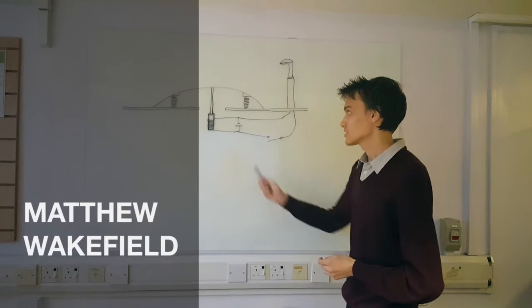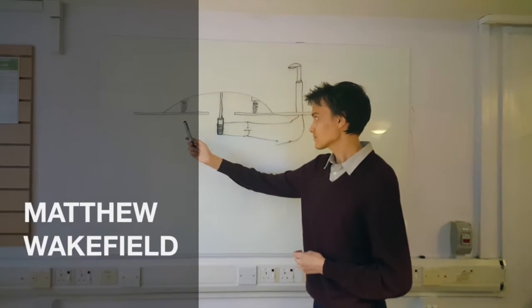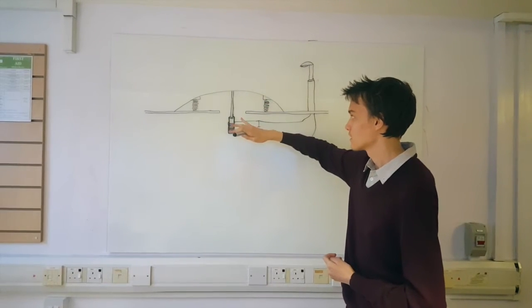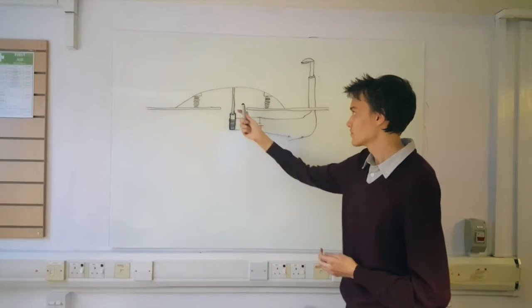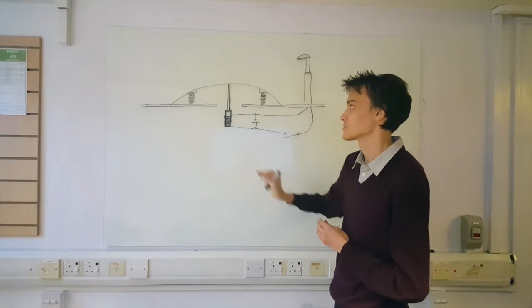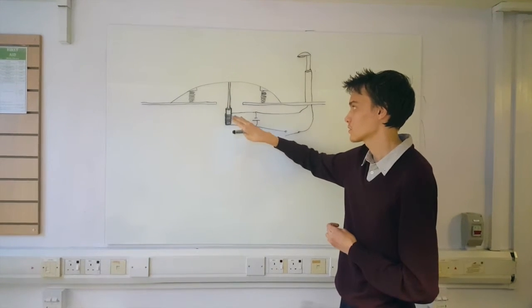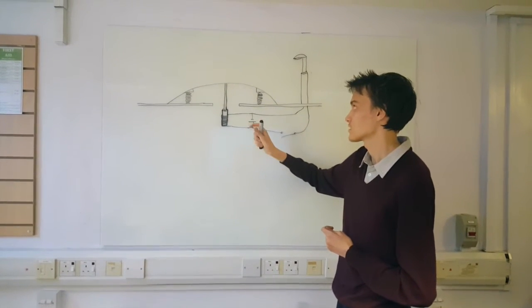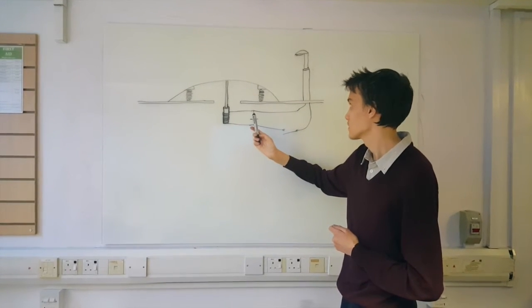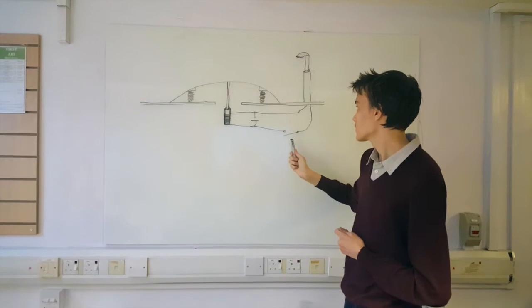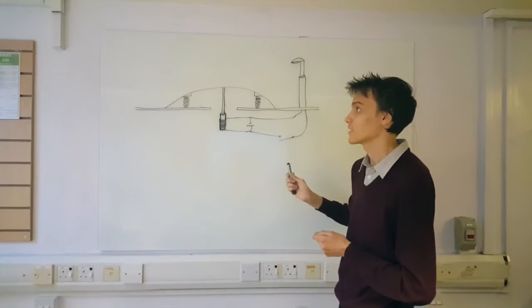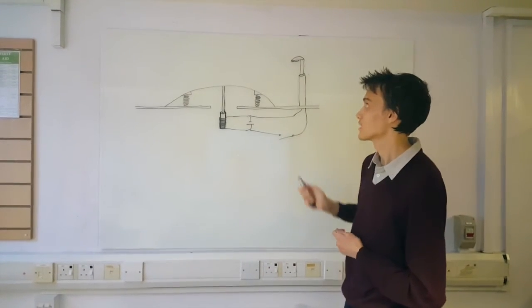Okay, so our idea is that as each set of wheels rolls over the speed bump, it gets pressed down, and magnets attached to the underside (we have 5, you can't see it because it's a cross section) pass through a coil of wire, which generates an electric current. The charge gets stored in a battery, and then at night a switch can be turned on, manually or by a daylight sensor, to power the street light.